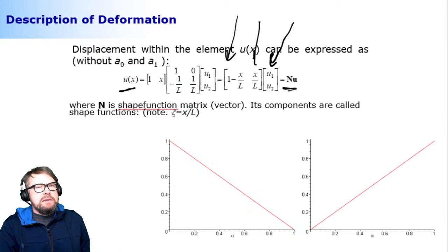You can make this polynomial expansion in a different way, and you could get a little bit different assumption of how the particles are moving. That's okay. And that's exactly what can be done in finite element modeling. But really what is important is to understand that there's a line between the nodal locations, and the line between the nodal locations defines how your finite element behaves.